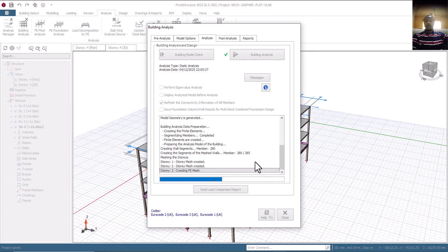And also, how do you know the thickness of your flat slab? It's very, very key, because based on code and principle, there's a requirement for that. For you to know the thickness of your slab, there's a calculation and a formula. There's a minimum thickness required, even though the area of your slab panel is, let's say, 5 square meters. Based on principle and code, for that 5 square meters there's an expected thickness it should carry. Then if you compare it with your own calculation, how do you come about your judgment?